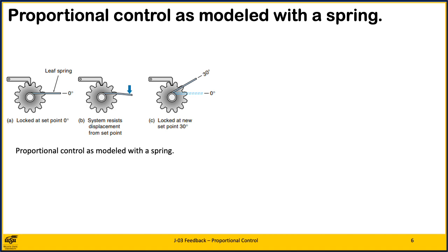If you had the opportunity to experiment with the proportional control system shown, you would notice that the arm has a springy feel. For example, if you were to push down on the arm, you would feel a restoring force, as if you were pressing on a spring. The more you displaced it, the more it would resist. What you're actually feeling is the control system's correcting force, where the resistance to movement is proportional to the error.